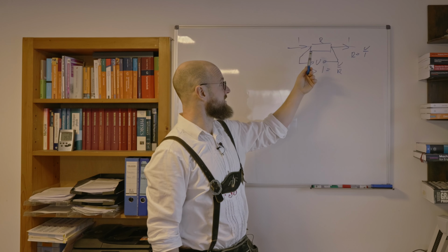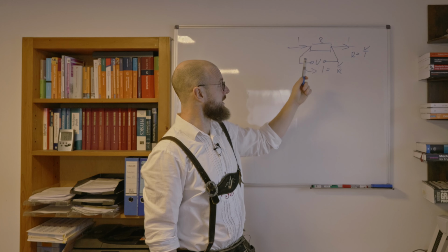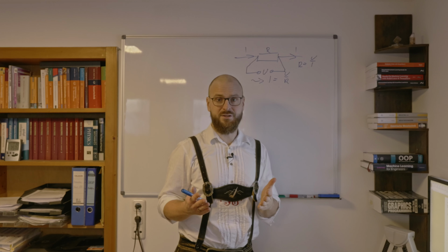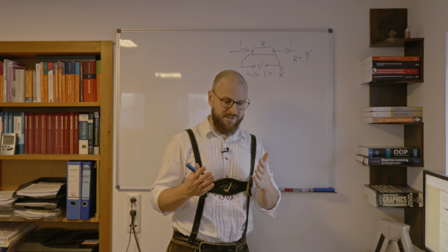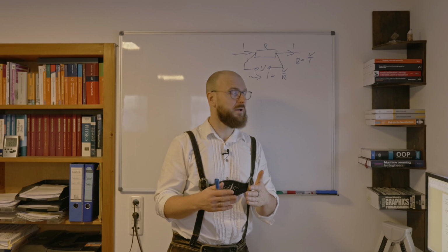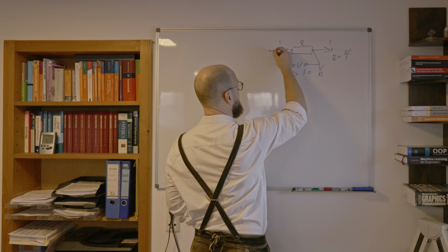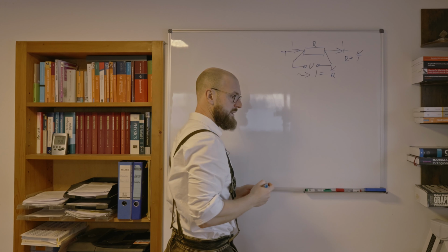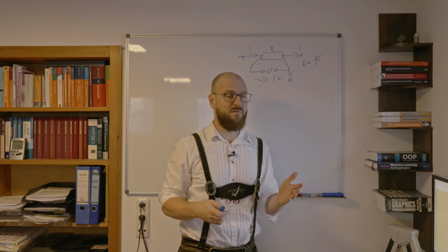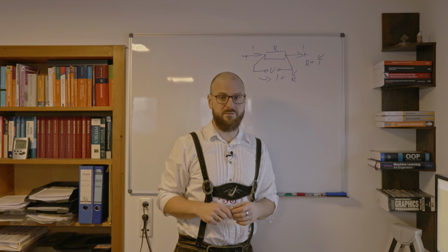What else to say about those sensors? One thing is, as I already painted, we should measure the voltage in direct vicinity to the ohmic resistor. So we should not connect the voltage measurement at those places, but directly at the ohmic resistor, to get rid of the resistances of the wires connecting the ohmic resistor.